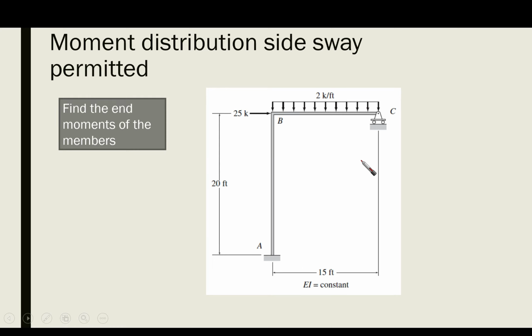Simply, as you can see here, at the horizontal line BC, there is nothing going to stop points B and C from moving laterally, especially as there is a concentrated load at point B, and there is a roller at point C. Even though member BC is inextensible, the axial deformation is negligible. However, B and C are going to move as a rigid body motion,